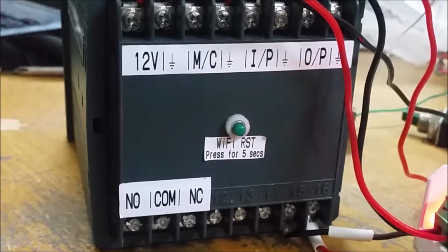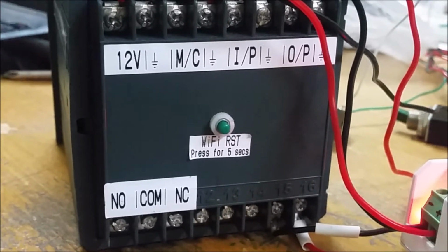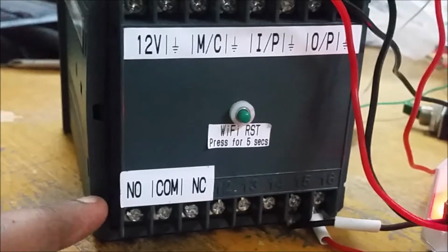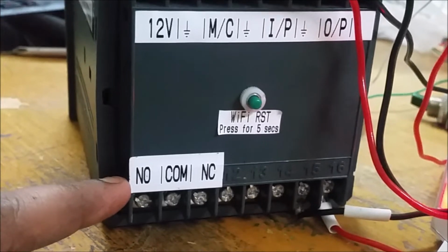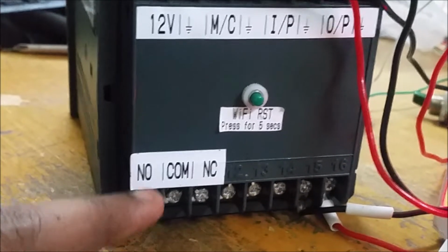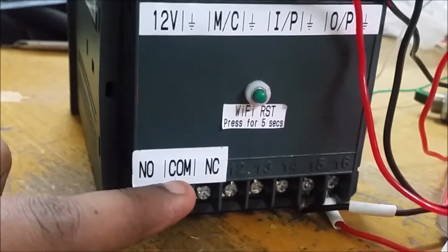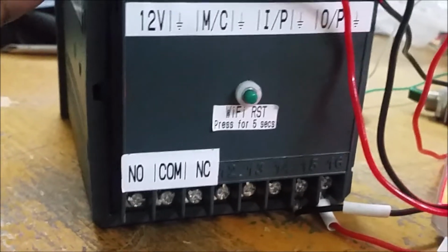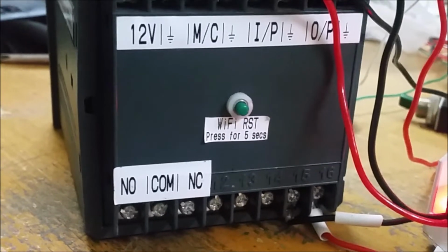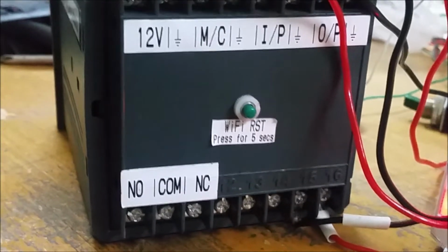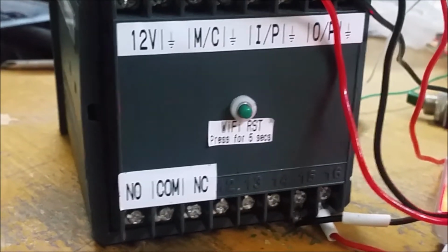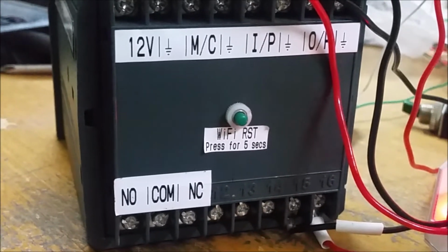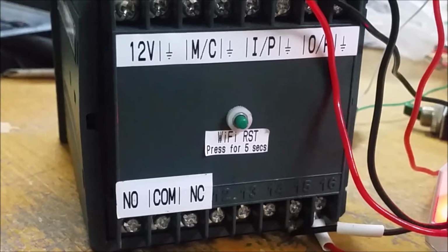And at the bottom, on the left hand side, are the terminals for the relay output that will control your machine supply across the common and normally closed terminals. When the machine status goes low, the device will activate the relay and open COM and NC, thus disconnecting power to your production machine. Only when the user has entered a reason code, the relay will be deactivated and the COM and NC will close, completing the power circuit of your machine.